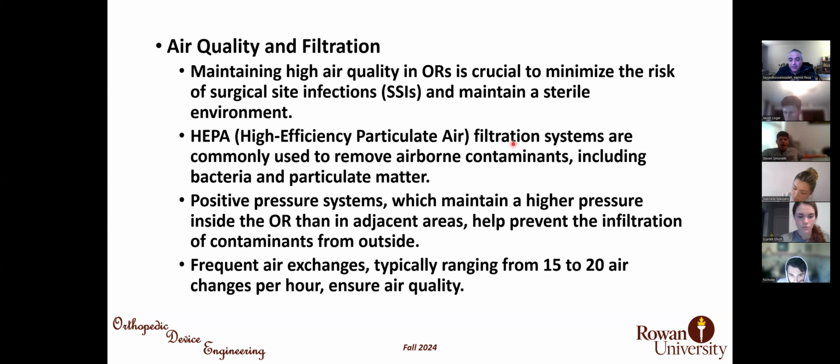So nothing by air can enter this room from outside. You can enter, but nothing can flow inside. For the operating room, it is very important to have a positive pressure system to prevent the contaminants in the outside environment from entering the operating room.